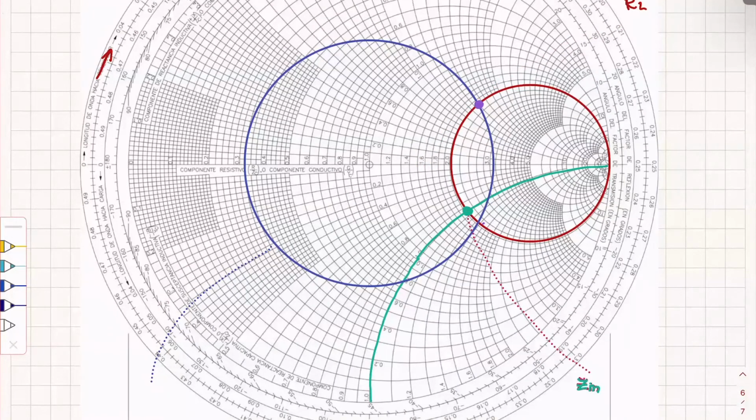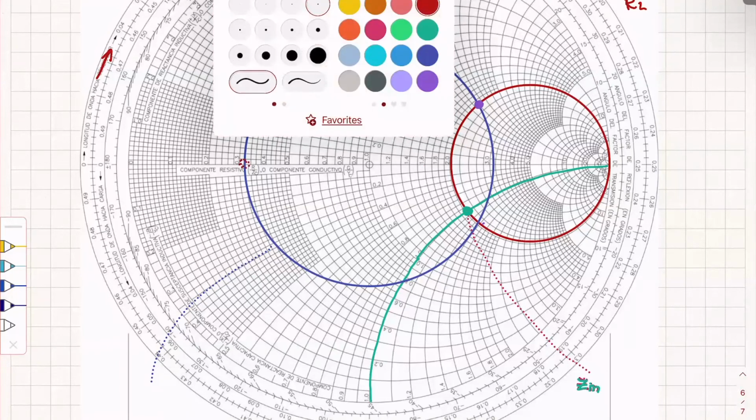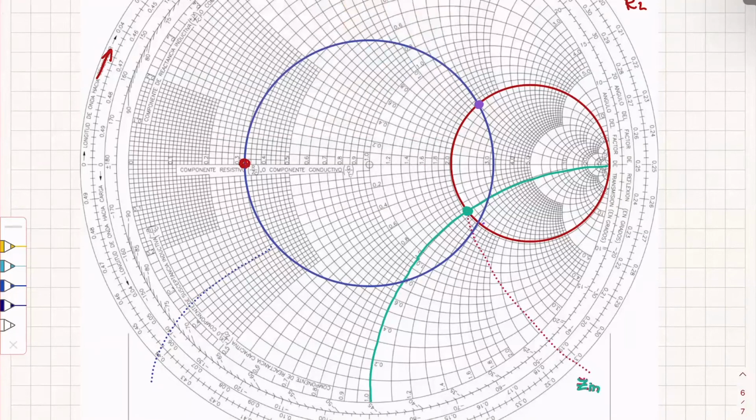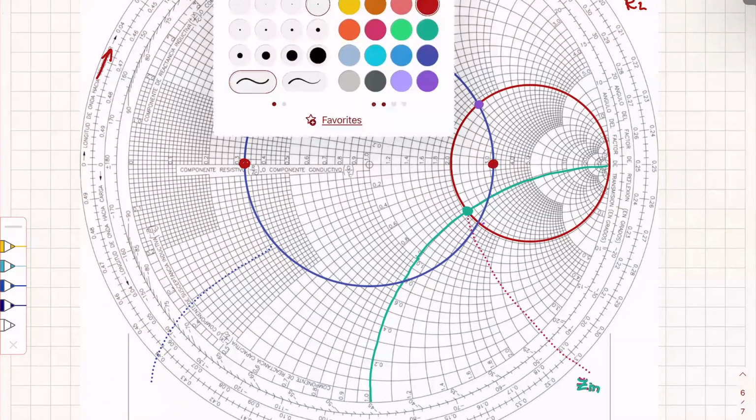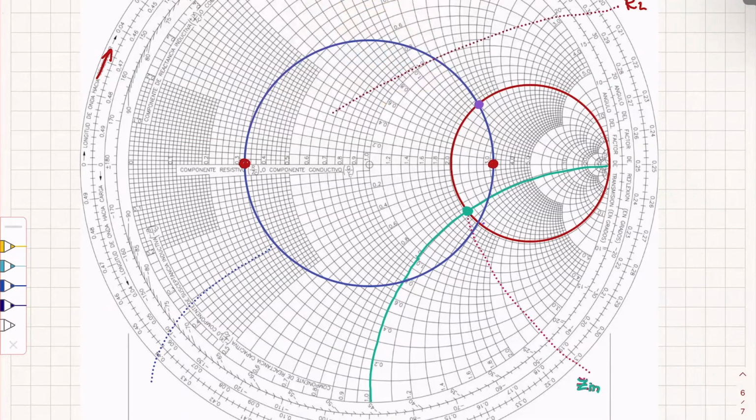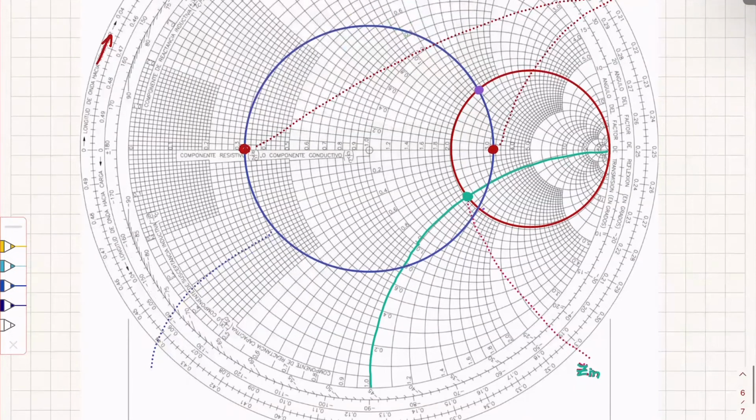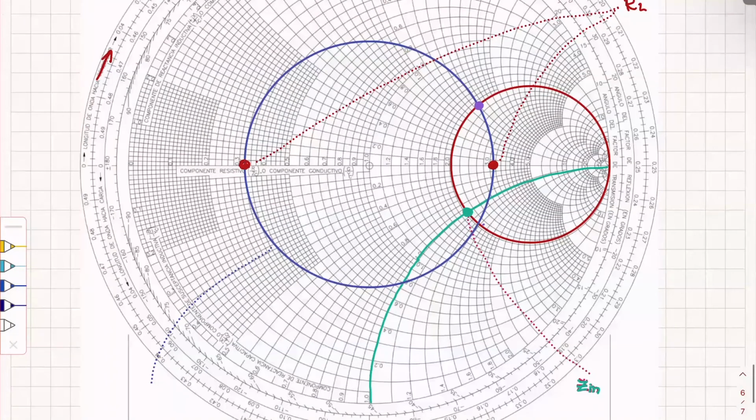the red point has to move either here, or there. If the red point moves here or there, then practically the blue circle is the circle that this point can move around. How then does my point move there? So my normalized resistance should be there or should be here, one of these points. How can it get it there? By changing the characteristic impedance of the line.